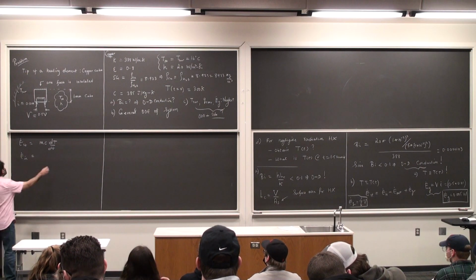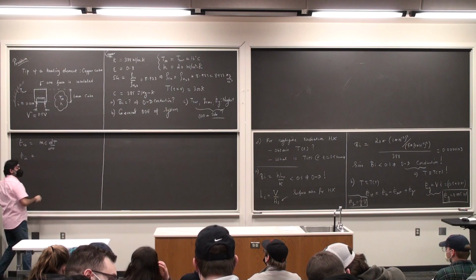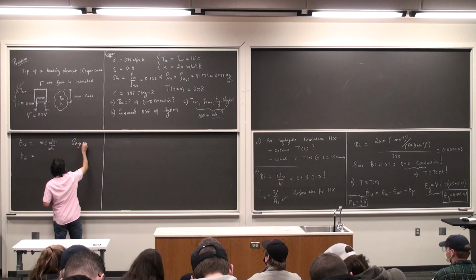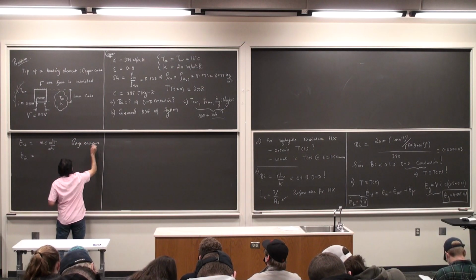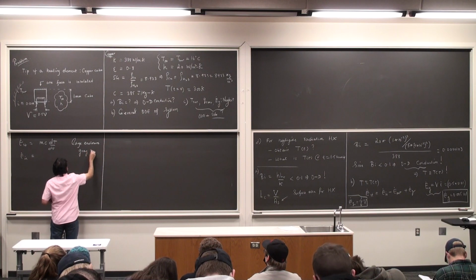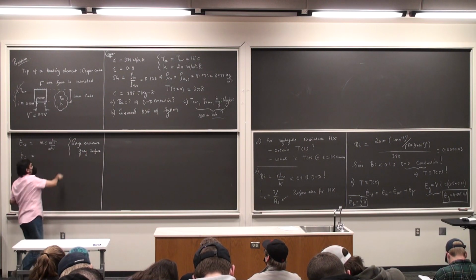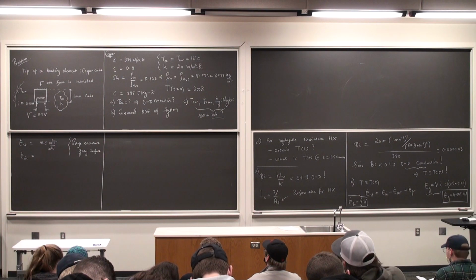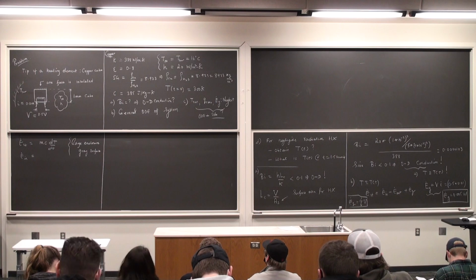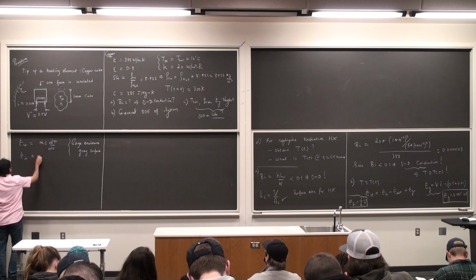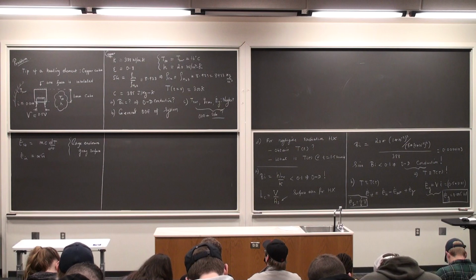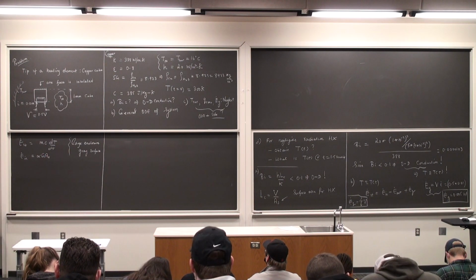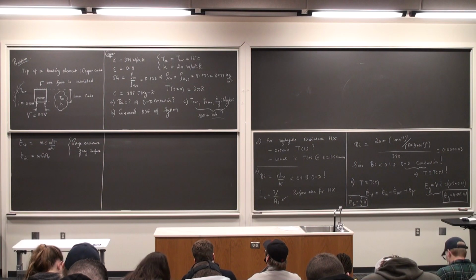Okay, so if I write E dot in, and if you assume a large enclosure with gray surroundings and a gray surface, and you'll see all of these being proved very soon using Kirchhoff's laws for radiation heat transfer. So E dot in is going to be alpha times the net irradiation times the surface area available for heat transfer. Alpha is the same as epsilon if you have a gray surface.